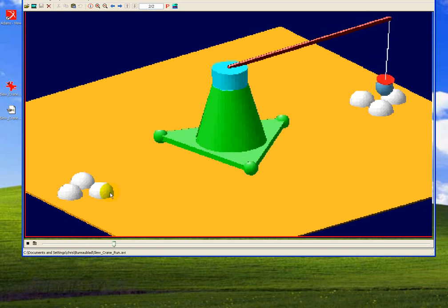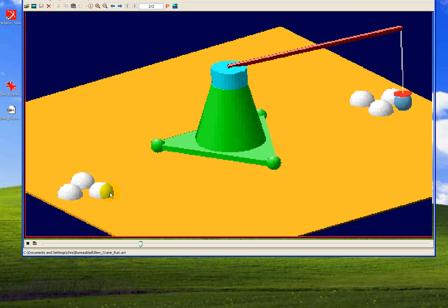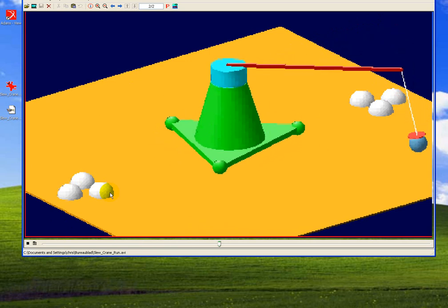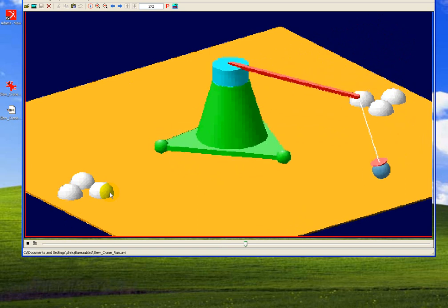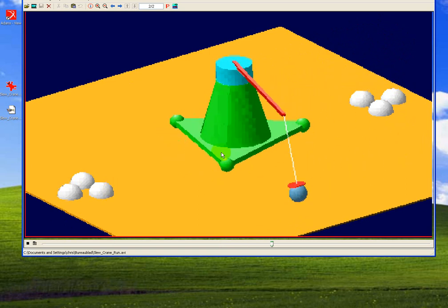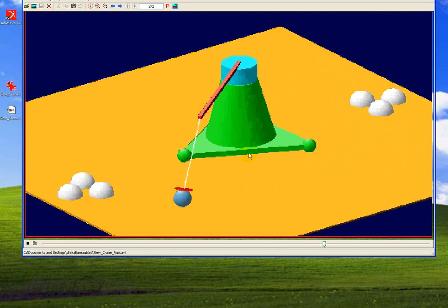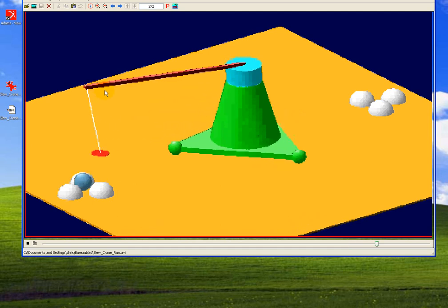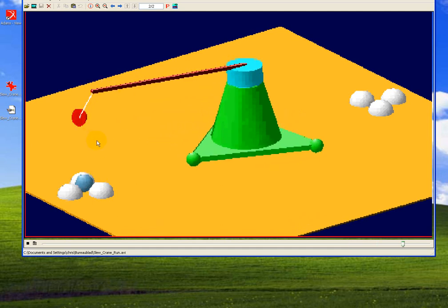As always, the biggest word with simulation and modeling is crawl, walk, run. Please do not start with making the complete model, including all complexities. A first good start would be to fix the base to the ground, not having it rotate and slide along, but try to get the modeling components for the cable and the clamp connection, and do that first, and after that introduce the additional model complexity of the sliding along the surface and the ability to tip over.